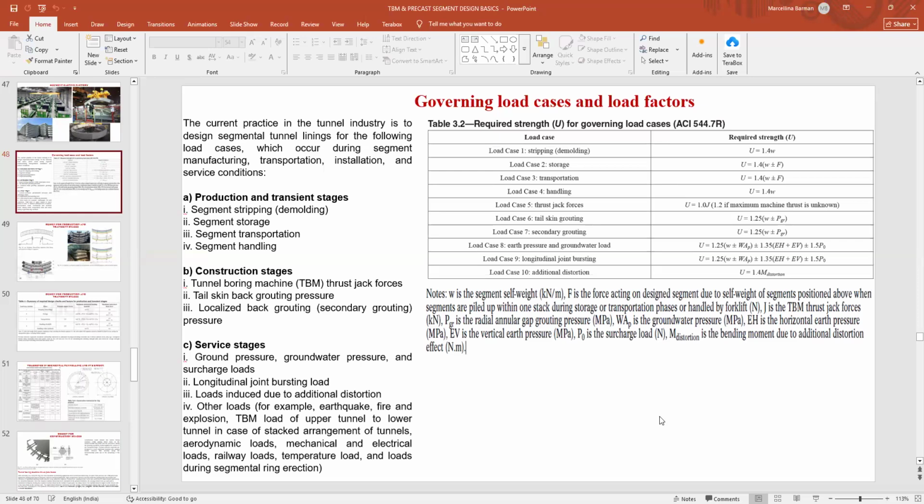But in the Haidar canal, over the 18-20 meter part, the client told that I want a very high exposure class because my durability will be very critical. We cannot change the thickness of the segment because our molds are already fixed. So what we did, we made all the reinforcement epoxy coated. So it is already considering the durability aspect.